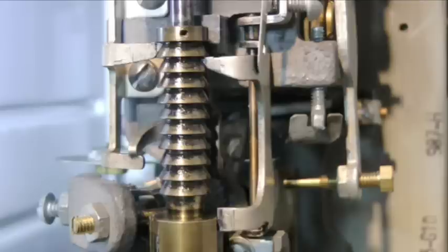The double dog vertical leg engages the vertical ratchet teeth, and the double dog rotary leg engages the rotary ratchet teeth. The double dog legs remain engaged with the ratchet teeth until the switch is released. The double dog vertical leg prevents downward slipping of the shaft between pulses during vertical stepping. The double dog rotary leg prevents anti-clockwise rotation of the shaft between pulses during rotary stepping and maintains the off-normal rotary position of the shaft for the duration of the call after pulsing is finished.